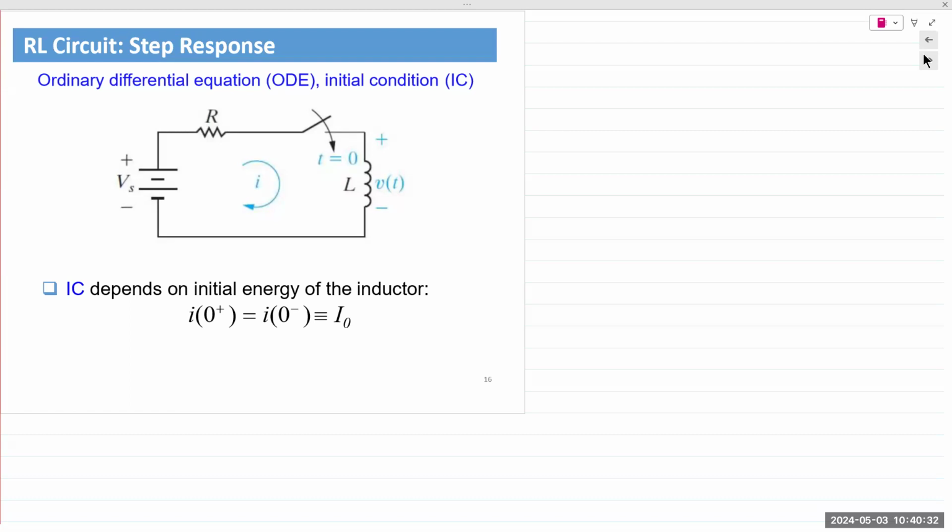Now it starts discharging again, but before it can discharge all the way to 0, it starts charging again because of an externally applied source. So when it starts charging again, there is some energy stored in there. Unless the problem states that the inductor or capacitor has been discharged for a very long time, you have to take that initial energy into account.